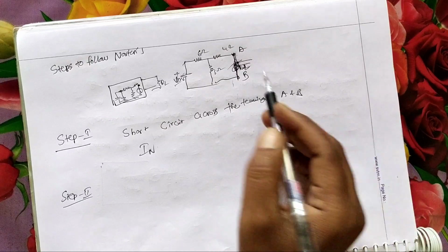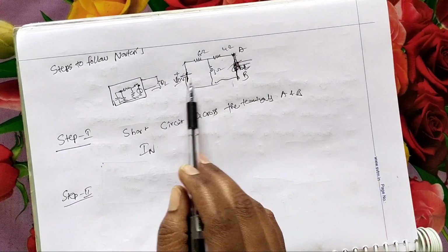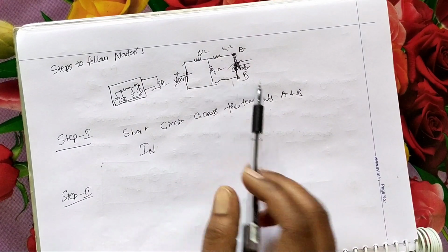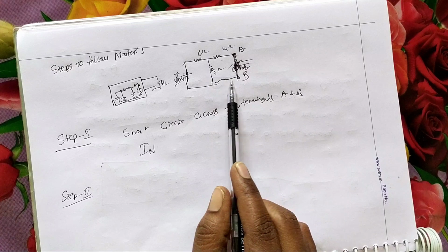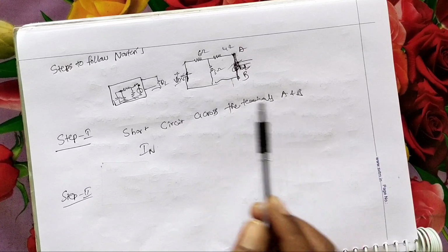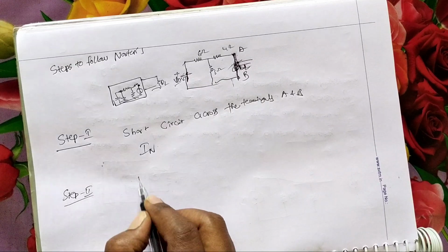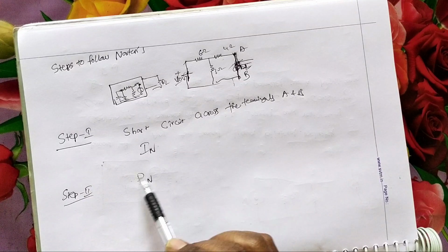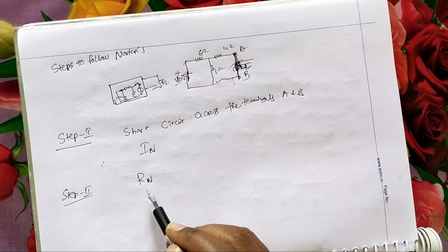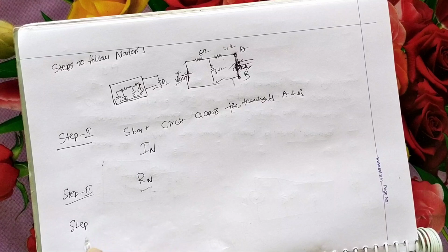From that, in Thevenin's theorem, the voltage source will be short circuited by its internal resistance. After that we are calculating Thevenin's resistance. Similarly, by open circuiting the load resistance where we want to calculate the current, after that we are calculating Thevenin's resistance. Similarly, we calculate Norton's resistance, similar to Thevenin's theorem. If you know how to calculate Thevenin's equivalent resistance, then you can calculate Rn. Rn is also known as Thevenin's resistance also.